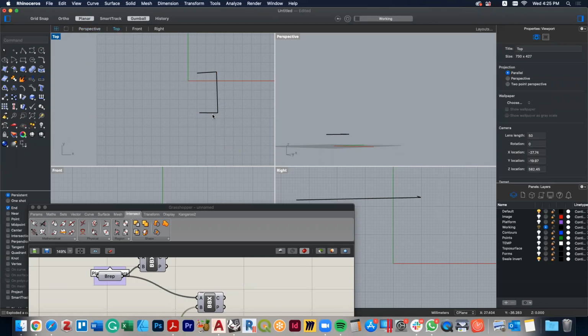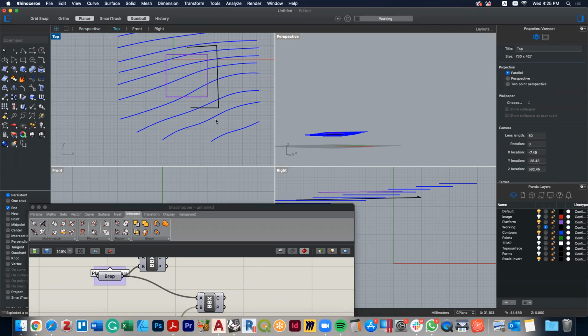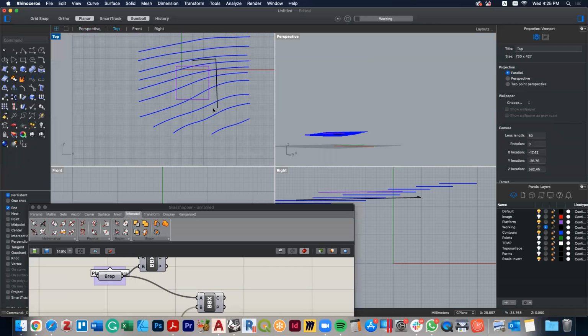Also, because the return we're not going to need, because when it's on the side of the slope, like if I turn the contours on and I turn the platform on, you'll see that in a way it's continuing down the slope. We wouldn't want to return it because we're going to make it into a hole. And in actual fact, we need it to go further than that. And so what I'm going to do is I'm going to delete that guy now.